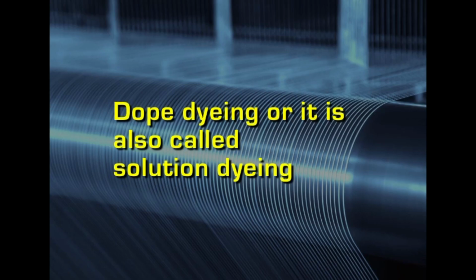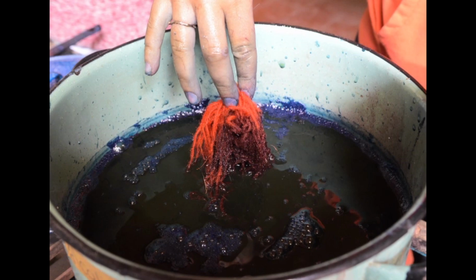the titanium dioxide. And especially for dyeing, when you dye the fiber, if it is too lustrous, you find that the particular color will not be looking very good, so delustering is compulsorily done for all dyed fabrics. Dope dyeing, also called solution dyeing because it is addition of the dye within the solution, is called solution pigmenting also.